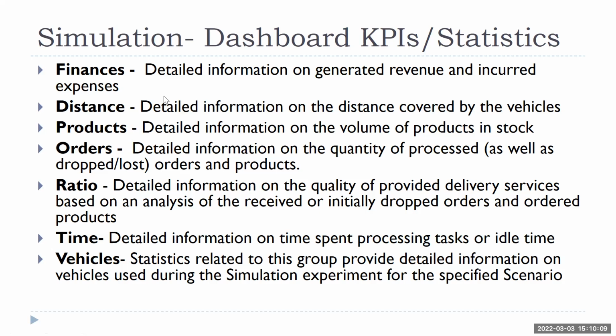Then I asked you what is the maximum distance, minimum distance. Then you analyzed the flow matrix, right? So the flow matrix is how it was calculated: number of pieces, number of requirements, number of demands from the customers multiplied by the average distance, right? So altogether for the 16 demands, you aggregated and you found that answer, right?